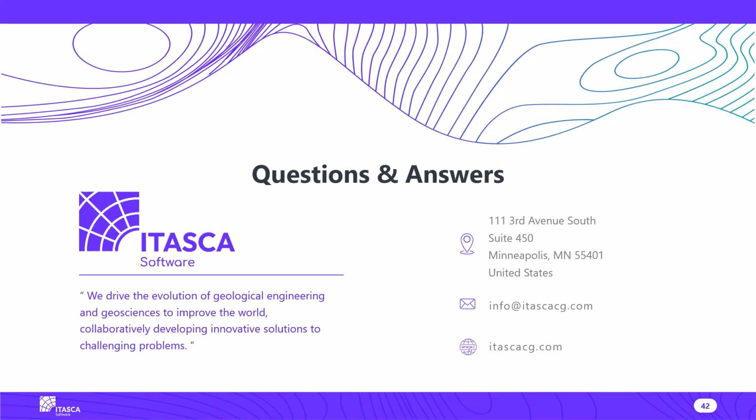So in this case, rather than studying the pillar by itself, you look at the convergence of the drift. Because as I said, the core of the pillar may be fine, but the convergence is already too large. And one thing that you need to keep in mind is that in this layout, some of the pillars may be failing, but then you have other pillars that may take that load. So it wouldn't necessarily mean, if you have a pillar that is not taking load, that you have a failure there, because the other pillars will take the redistributed load. So as I said, the core of the pillar may still be holding some stresses, but if the outer part of the pillar that has to do with the faces of the drift collapses, then of course you have a stability issue in the infrastructure.